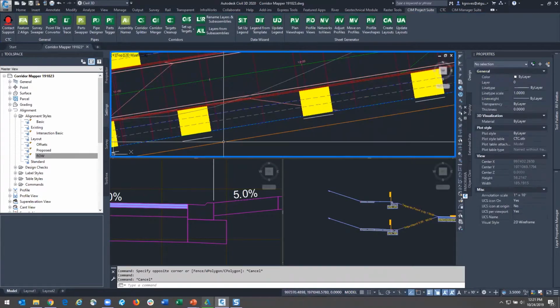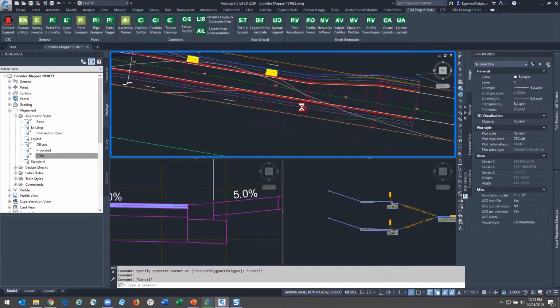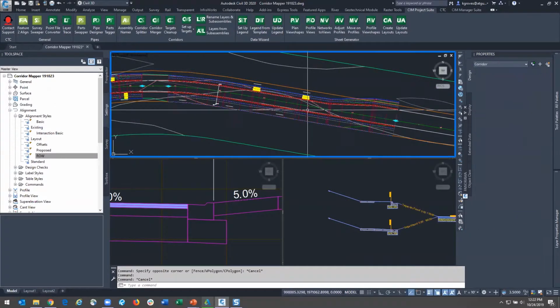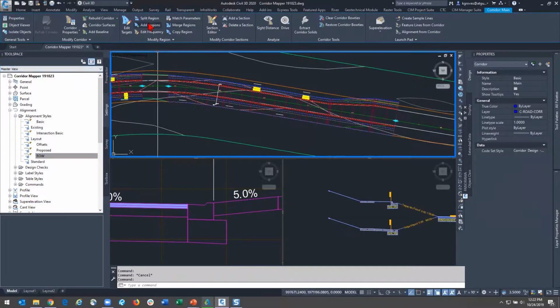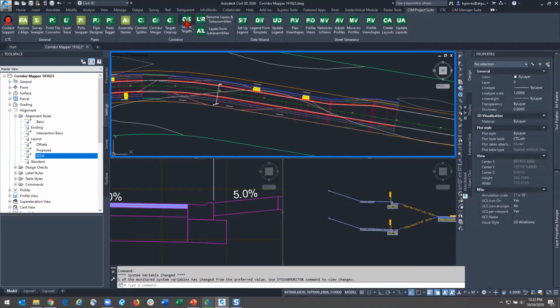I can also see that in the second region where I actually set up those targets for my driveway / boulevard situation, I've gone out to meet that right of way. If I wanted to assign that in the previous one, I'd have to go through and either copy these properties over or go back into the corridor mapper setup dialog and grab those. I'll just keep moving with the second region for the rest of the webinar.